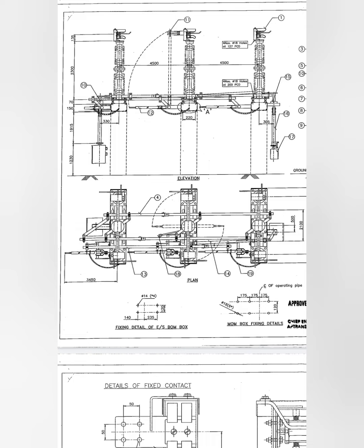So next is your with earth switch type of isolator sets. In here we have an isolator operating box or operating mechanism separately, and for the earth switch we have a separate operating mechanism box, and also the operational shafts and rotating shafts will be parallelly connected, with your isolator on one side and earth switch on the other side.